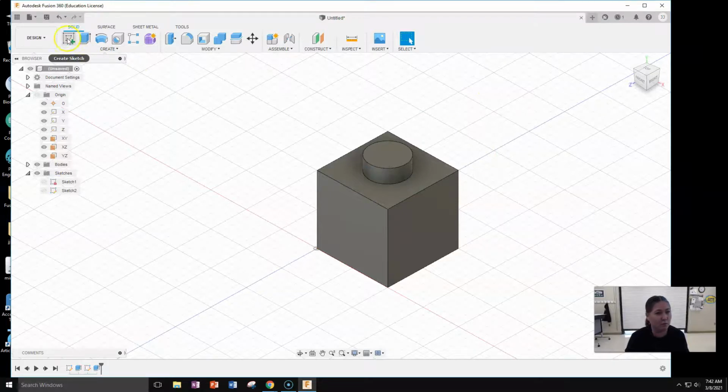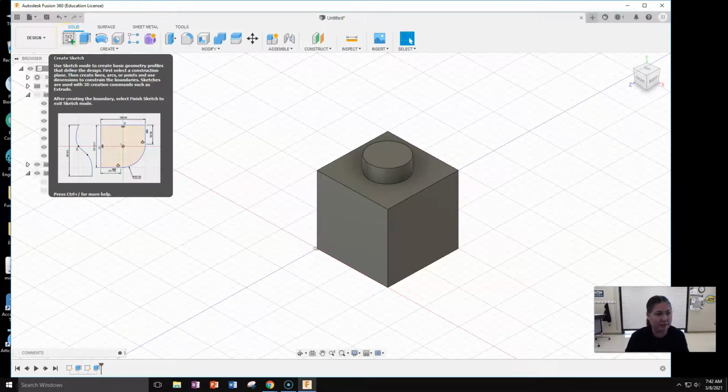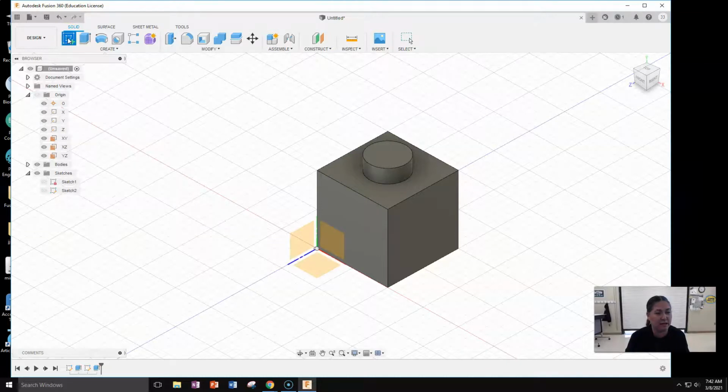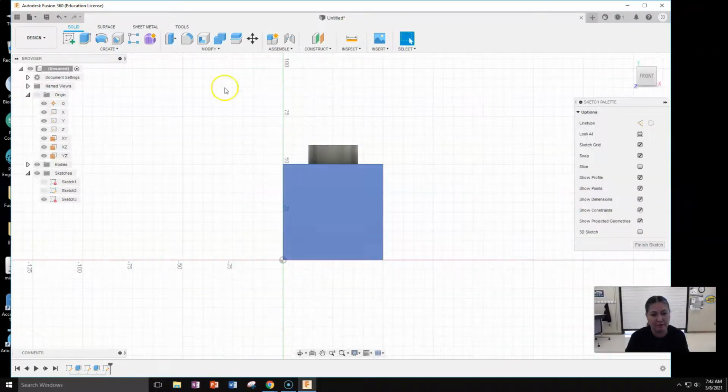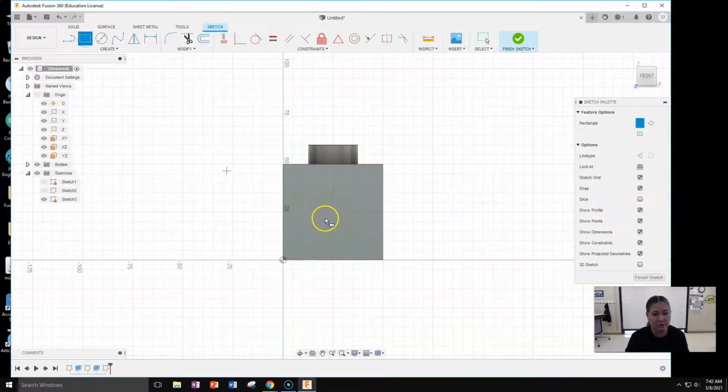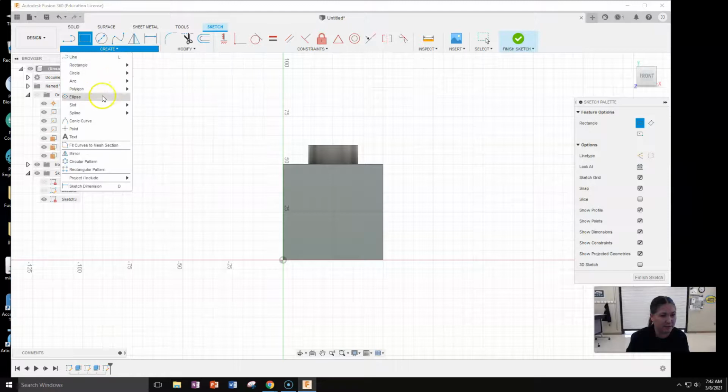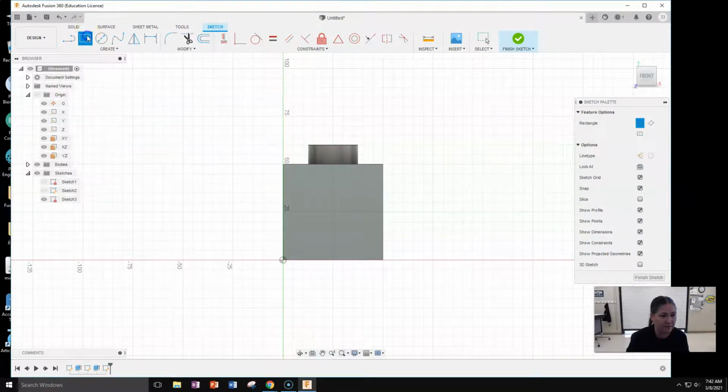All right, we'll do one more and then we'll call this until I get a better recording situation. Let's add a new sketch. I'm clicking up here and we'll put it right here in the front. Let's do another rectangle. Let's see if we can choose a different rectangle. Can I? I probably can't. It's going to be stuck there. Okay, so we'll use the 2-point rectangle.